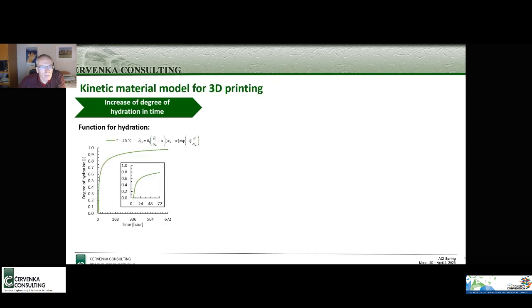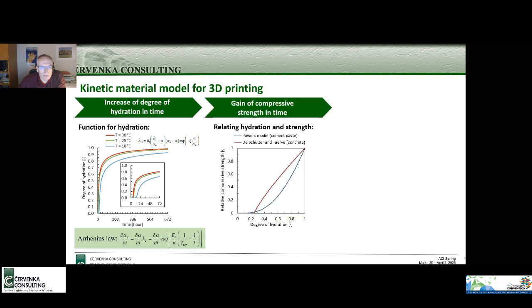We can directly build it up based on this G-code, which contains basically the coordinates of the moving of the printing head. And of course, an important part is the modeling of the hardening of the fresh concrete. For that, we have two possibilities. Either we provide directly the time-dependent parameters for our material model, or we can generate them based on the hydration curve, which is maybe the most suitable and easiest approach.